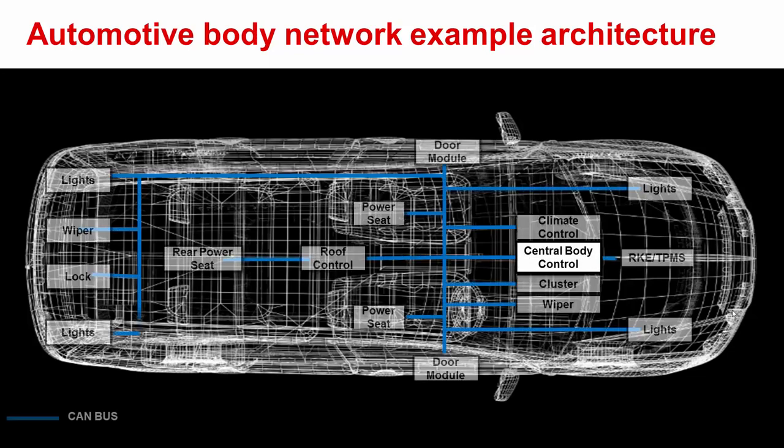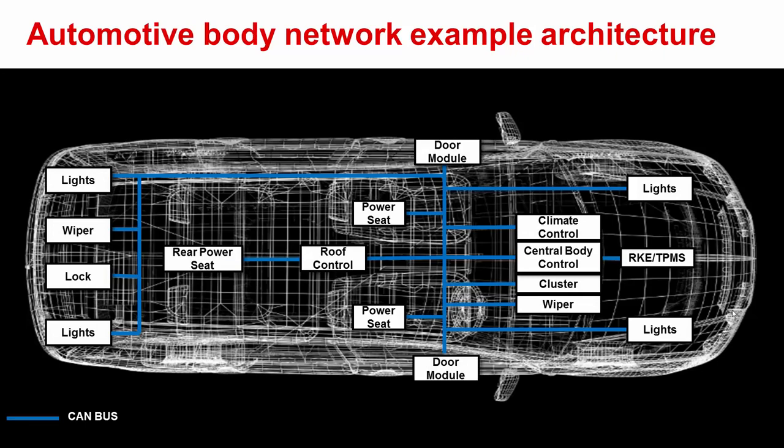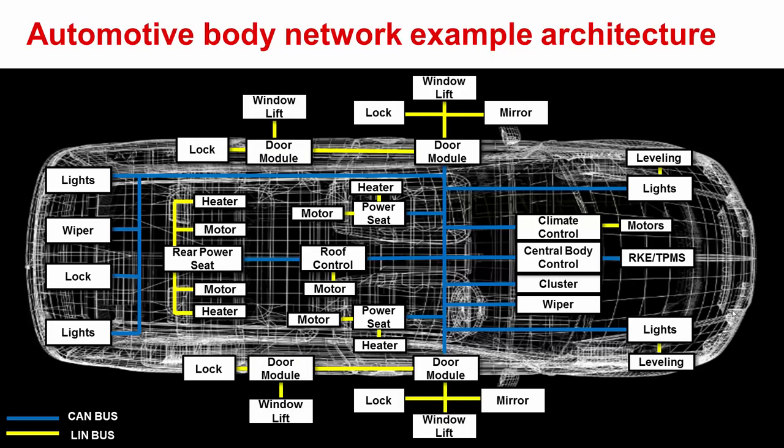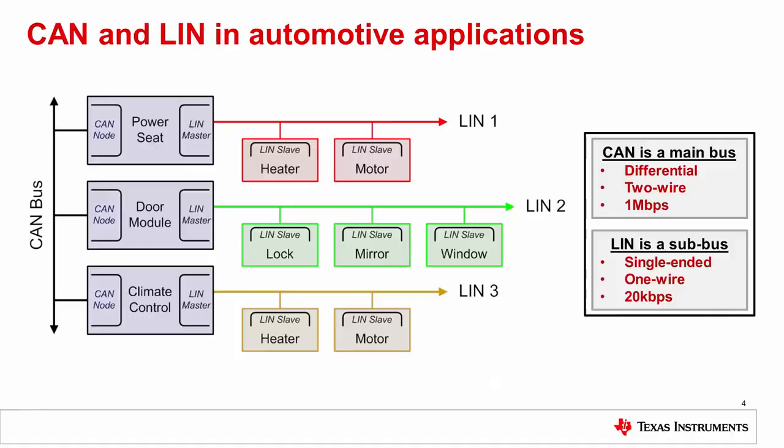The CAN bus allows for components to talk to each other seamlessly in the automobile. The LIN bus allows for further expansion to peripheral devices. This bus hierarchy was designed to save costs in wiring. Wire is one of the most expensive components in a car. It's heavy and often made by hand, which can cost lots of money. Anything that can be done to reduce wiring is done.